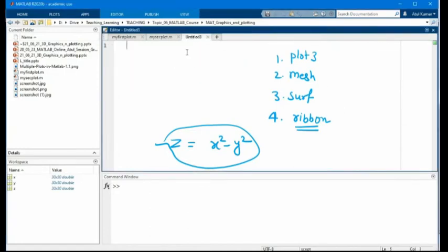So what we have to do, let me take one command. So here also I will write clc, clear. I can apply the previous one also, and I can take a new one. Okay, so x and y we create by peaks, 30 cross 30 peaks.